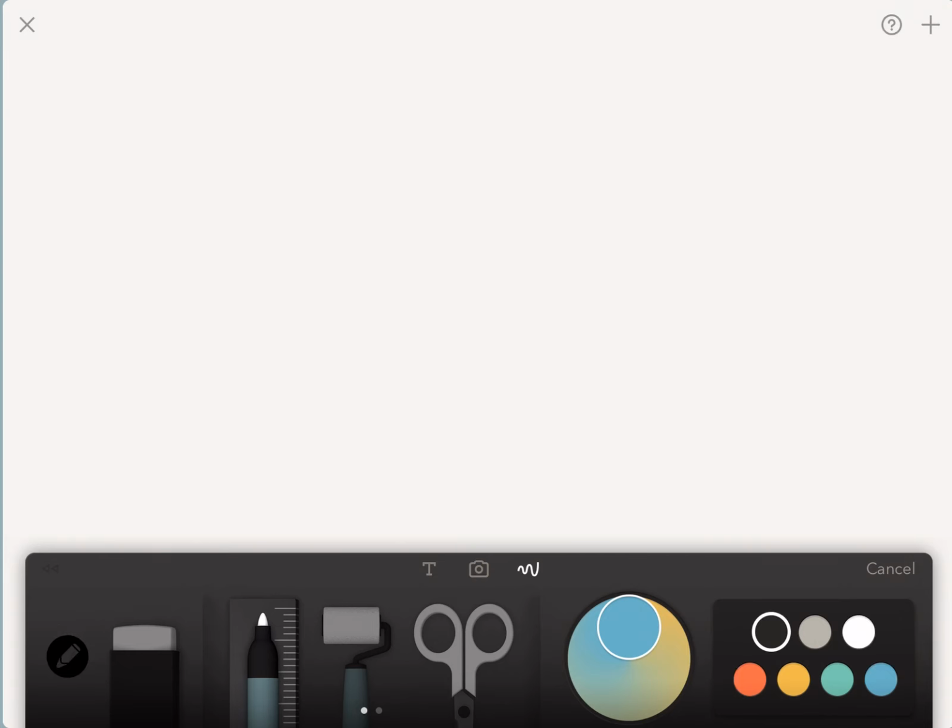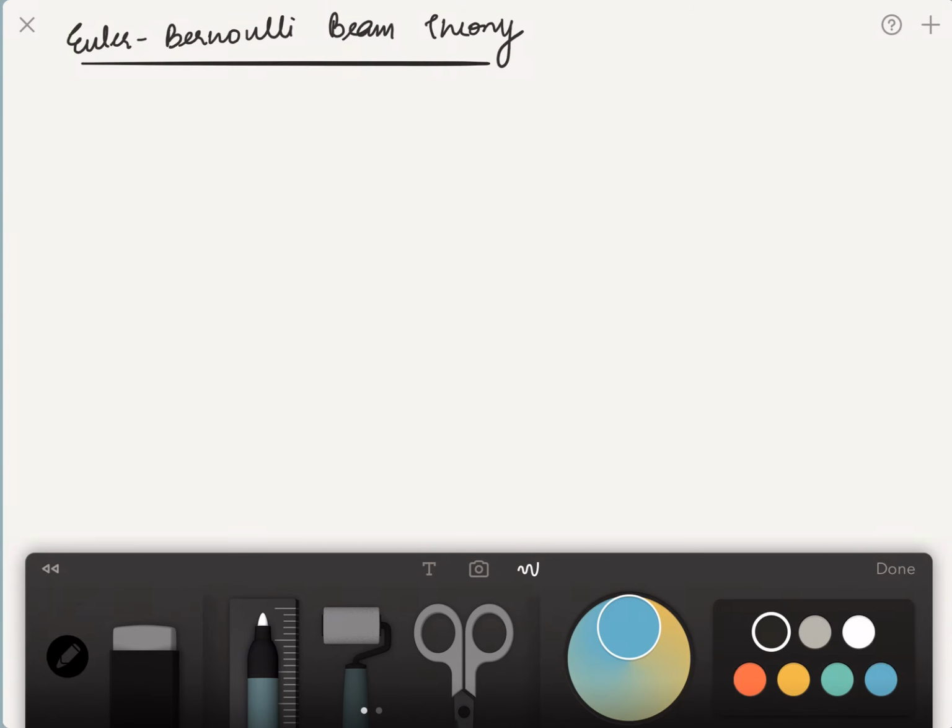So continuing, let's start talking about stiffness of a beam. Let's say I just want to discuss general Euler-Bernoulli beam theory. That's what I should call this section, Euler-Bernoulli beam theory. Now, Euler-Bernoulli beam theory enforces certain conditions in beams. The most important condition that the Euler-Bernoulli beam theory follows is that we are only going to consider bending deformation. So I'm going to write here bending deformation only.